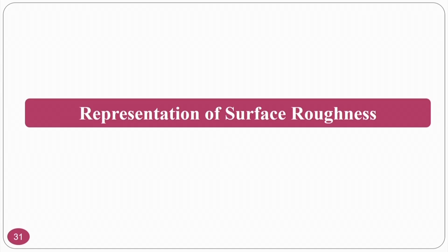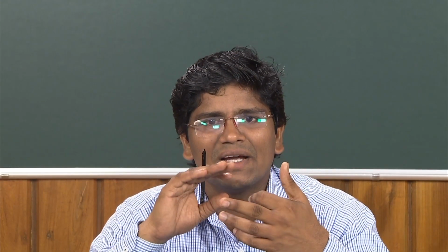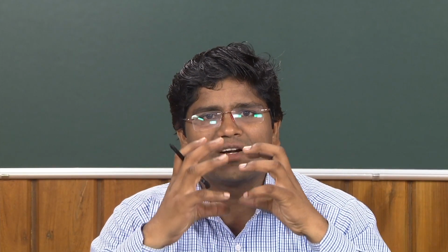The representation of surface roughness: now you have measured the surface roughness and you want to go further, how to represent it. Assume that I want to have a milling surface represented. I want waviness representation. I want what type of lay, that is, the predominant direction of surface roughness, whether it is a milling lay or a parallel lay, perpendicular lay, cross hatch pattern, how to represent all these things. That is most important for abrasive processes. Okay. So, how do you represent?